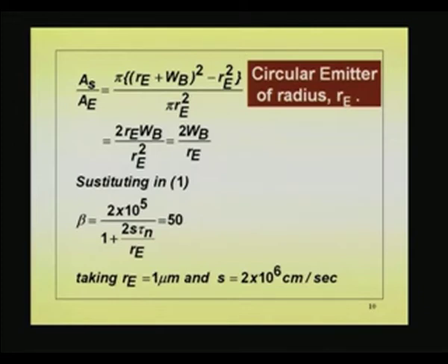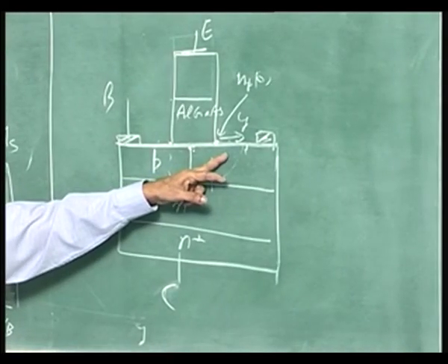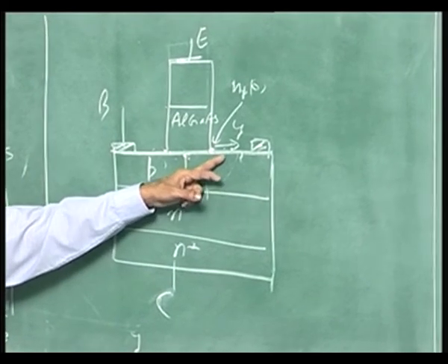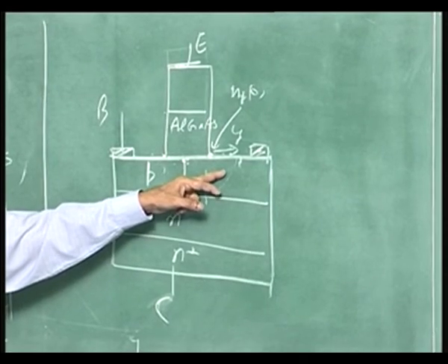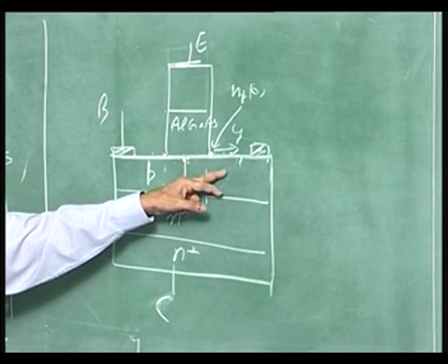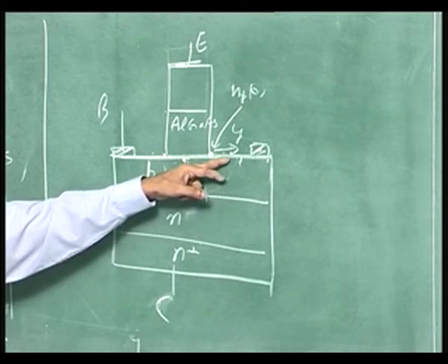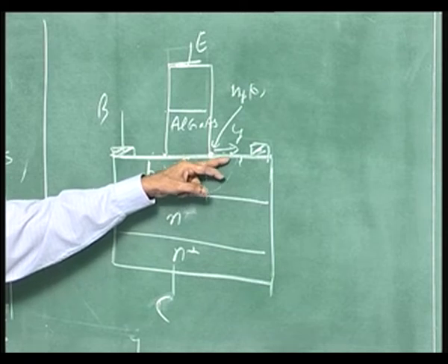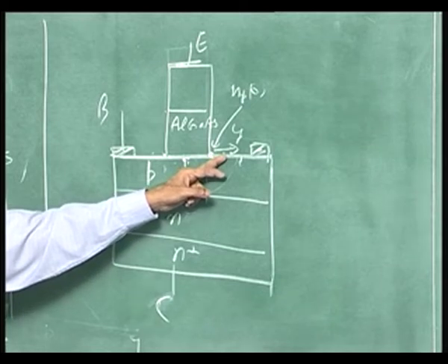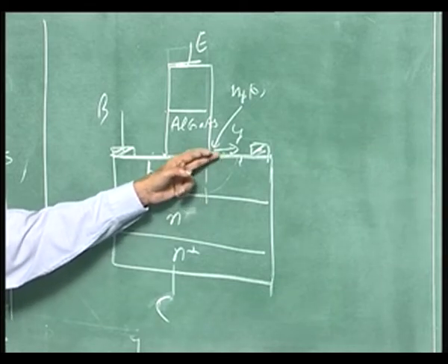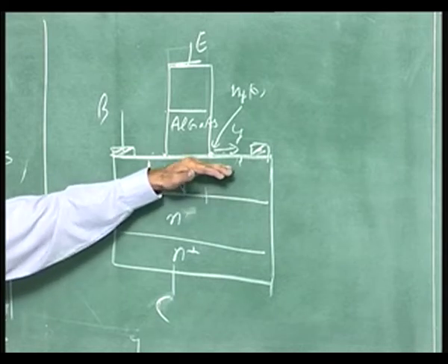The surface recombination velocity is large because there are a lot of dangling bonds here. These atoms in the bulk, they are surrounded by 4 neighbors. So, all those bonds are tied to each other, there are no dangling bonds. Whereas, here the atom sitting on the surface has 3 neighbors below, no neighbor here. So, a dangling bond is up there, which is very highly reactive, and that is the one which acts as a recombination center. It is a deviation from the periodicity.